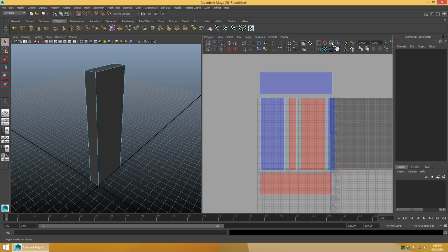Here I'm enabling the shaded UV display. Since the planar projections are performed in a single direction, some of the projected faces will be flipped, indicated by the red shading. These will need to be manually corrected, otherwise the diffuse and lightmap information will be displayed on the inside of the mesh instead of the outside.